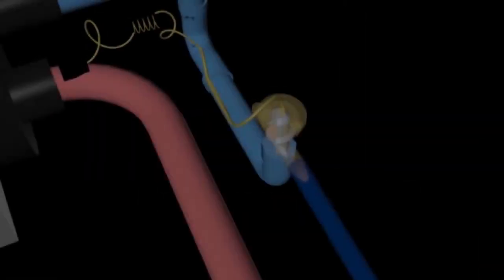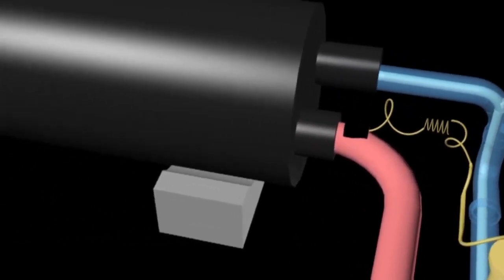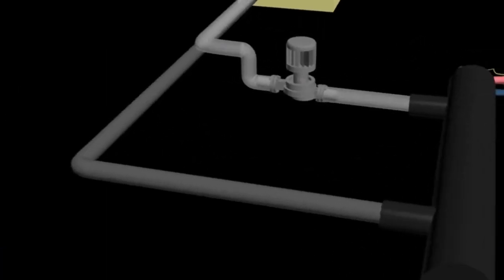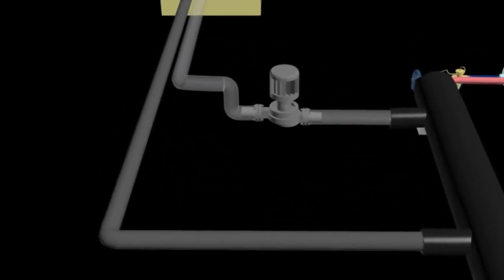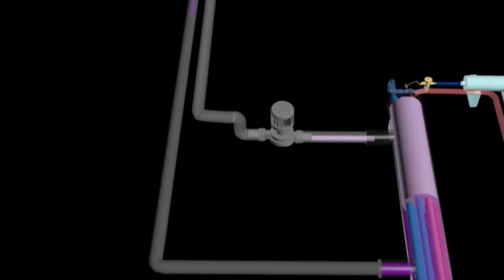Evaporator. The refrigerant in low-pressure liquid form coming out from the expansion valve will flow into the evaporator at low temperature. In evaporator, the heat from the chilled water which comes out from the air handling unit will be absorbed by the refrigerant due to the temperature difference produced.